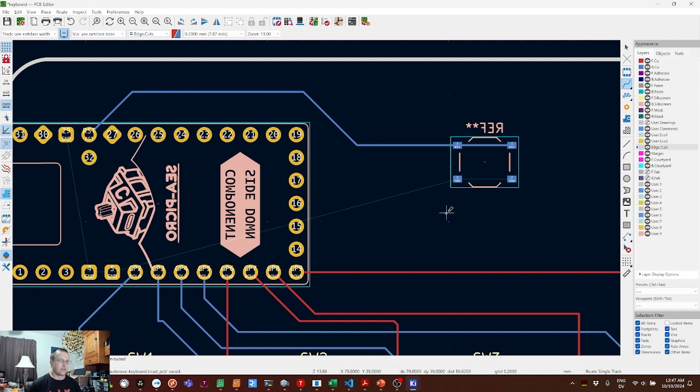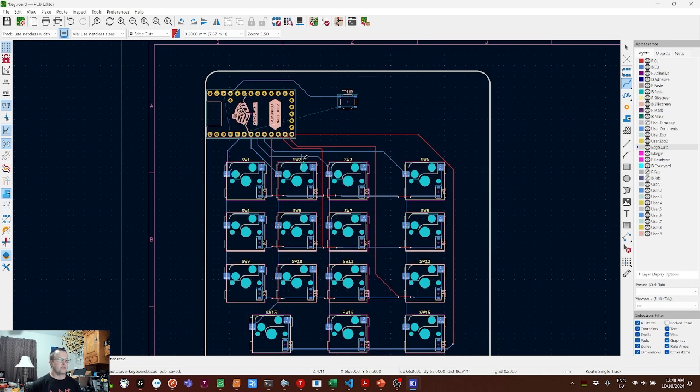All right, we're not going to connect the ground pin though. We've got a couple different ground pins to connect. And one of the best practices for designing circuit boards is to basically use all of the copper layer of the board as what's called a ground plane. Basically one giant chunk of copper that's all connected to ground.